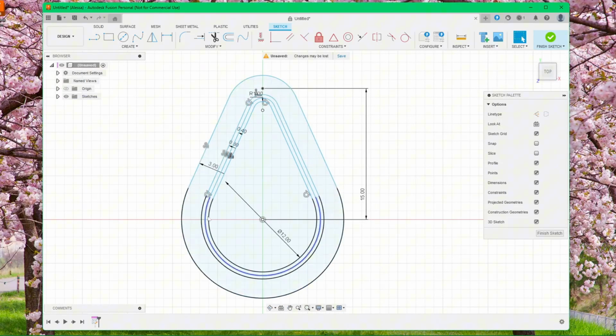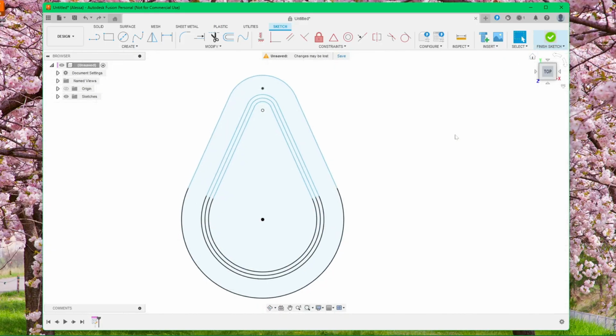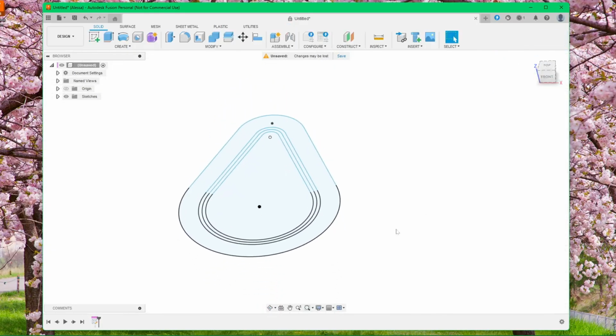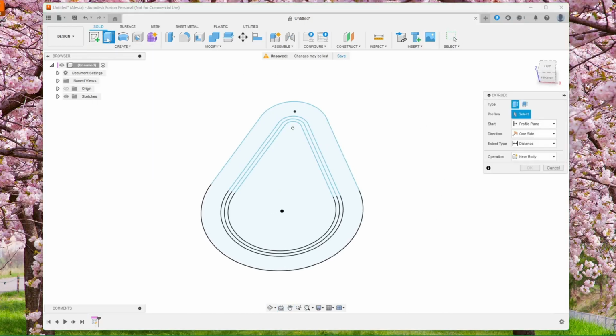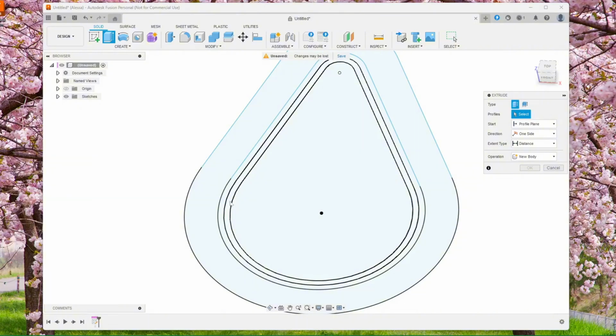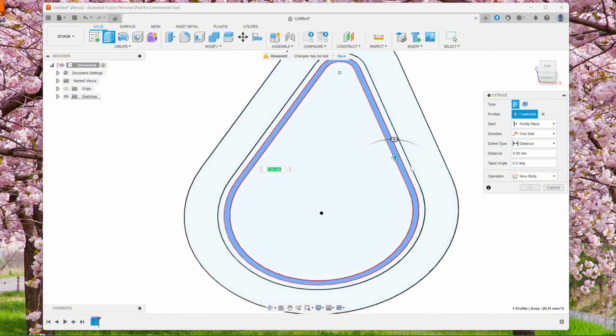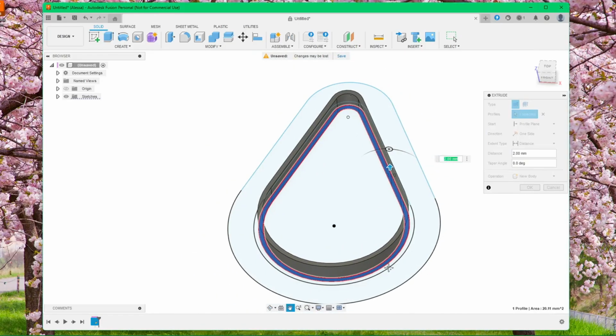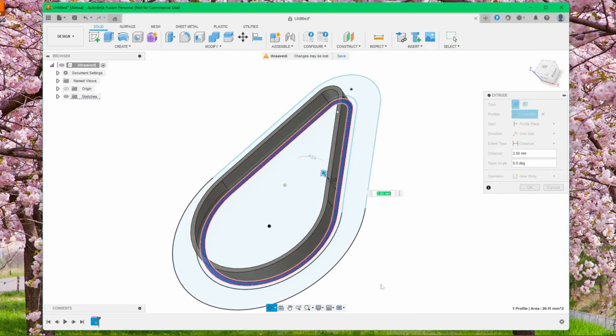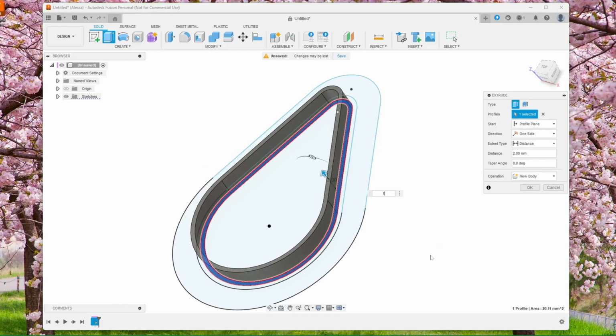We will now extrude these contours to make it a solid object. I will show you how to do this. Go over to Finish Sketch, rotate your view a bit, either with the cube or with Shift and your mouse. Click Extrude. Select between these two lines, like this. Use the arrow to drag it out, and enter 15 millimeter.